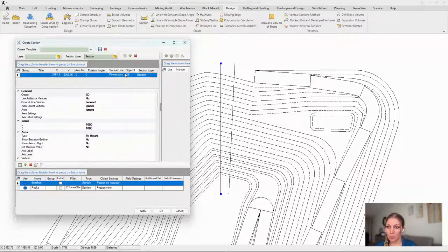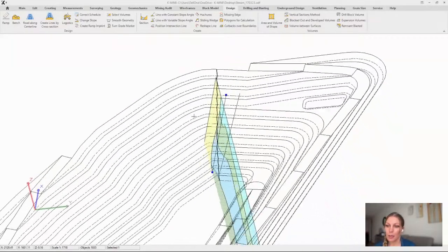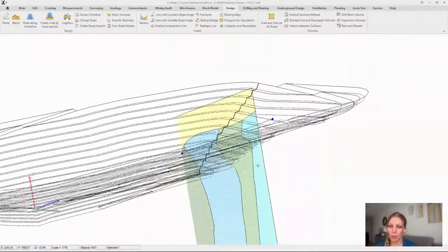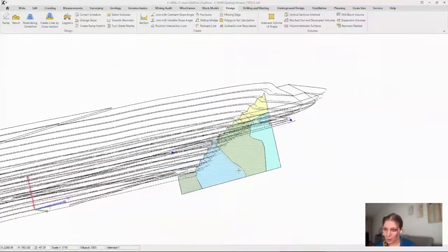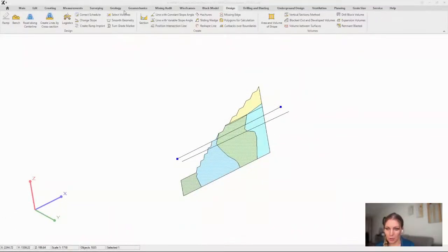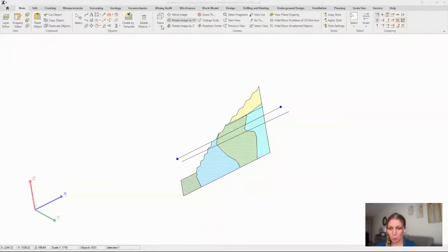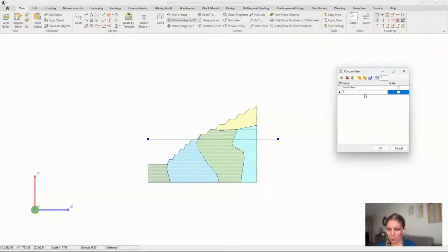The stability calculation, which utilizes FEM, is performed section by section. So this allows us to utilize the criterion section tasks to obtain a slope section that takes into account the mining location and the rock formations. We trim the superfluous portions of the sections and switch to the working view. And then we initiate the FEM stability calculation task.